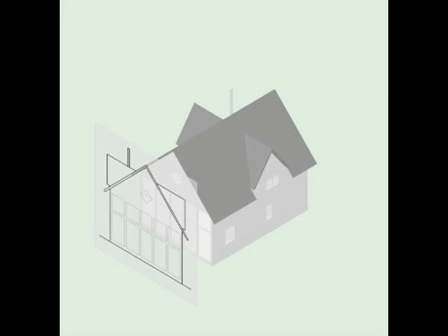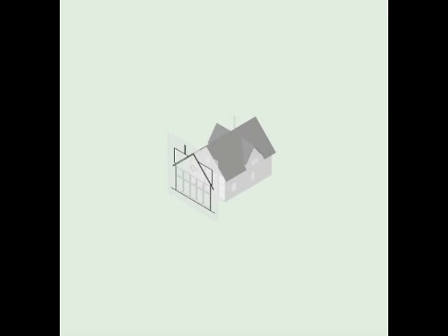To show a building's relationship to the ground plane, building elevations should include a section cut through the ground mass at some distance in front of the building. We need a number of related elevations to fully describe the exterior appearance of a building.